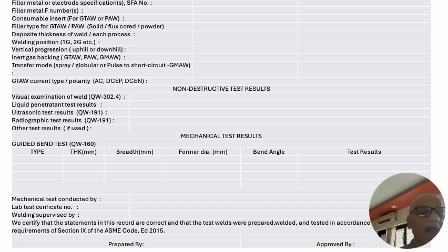performance. And then come the non-destructive testing results which are required as per the data, and it is good to once again attach the report of ultrasonic or liquid penetrant or any visual inspection. You have to do it very carefully. The reinforcement has to be measured, penetration has to be measured, and the ripples, if you can count per centimeter or per 10 centimeters, you can record it.